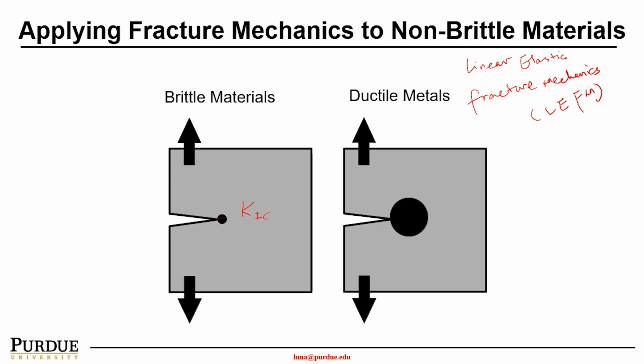In ductile material, because your K1C is high, you have a higher G critical, or G1C, right? Your critical energy release rate is higher, so the tip can be blunt, and you can take a large stress for the ductile material, and the deformation will be substantial.